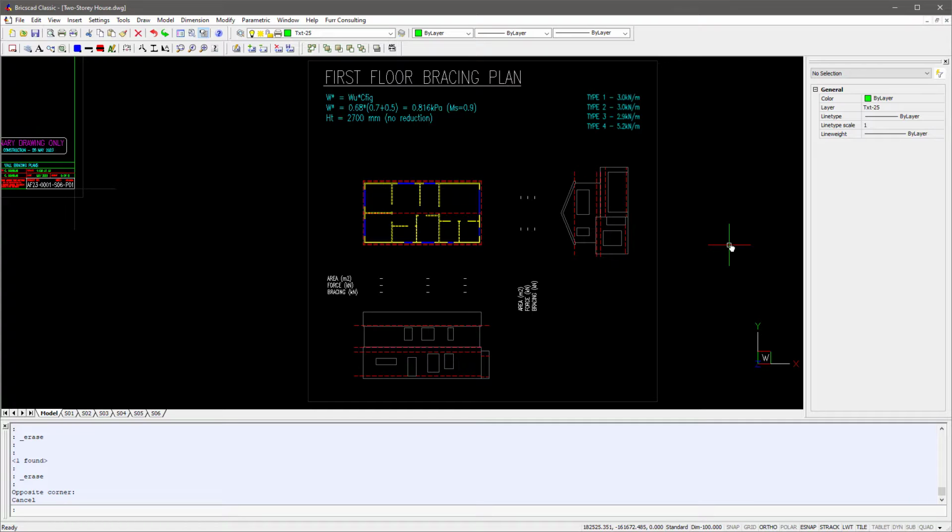Now, to make sure we cover the requirement that the bracing is distributed somewhat evenly across the house, rather than just taking the total area in one direction and specifying enough bracing to meet the resultant force, what we will do instead is break down our area into multiple areas in one direction. Getting a feel for how to set out areas does take a bit of practice, but the general idea is that we will want to centralize areas around walls we will use for bracing. This idea should become clear as we progress along.